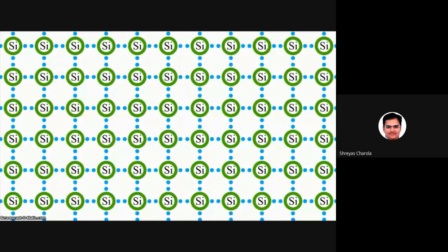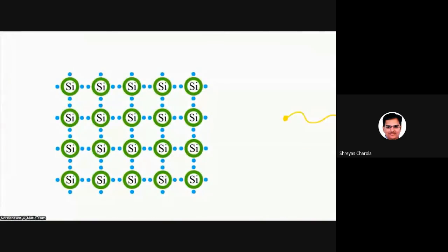Here we have a silicon crystal. If energy is added, for example, a photon can hit a silicon electron, the electron may get enough energy to break its bonds and actually leave the atom completely. In the bond where the electron used to be, there is now an empty space. That spot on the silicon atom now has a positive charge, and other electrons are attracted to it. Every time an electron leaves its spot to fill the empty space, it itself leaves an empty space back where it was before. If we apply a charge, we can see that although all electrons are attracted to the positive, only the ones by the hole can move closer.